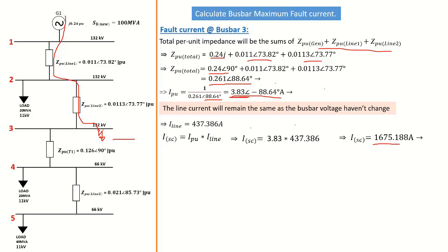So if someone has to come and touch here, that's the current that will flow from that busbar into the ground. Or anything has to happen to cause that short circuit to take the shortcut. That's what it's called. It takes the shortcut instead of going down this way. It now takes the shortcut straight to earth. So that's the magnitude that will be available, that 1.6 kiloamps.